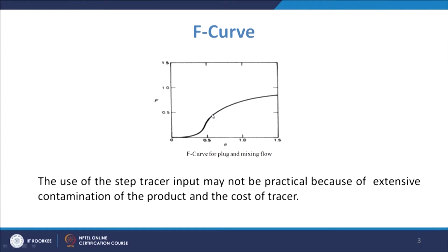Now, use of the step tracer input may not be practical because of extensive contamination of the product and the cost of tracer. So, it is not very much in practice, except we can certainly go for numerical analysis of these processes where we do not require these expensive tracers.